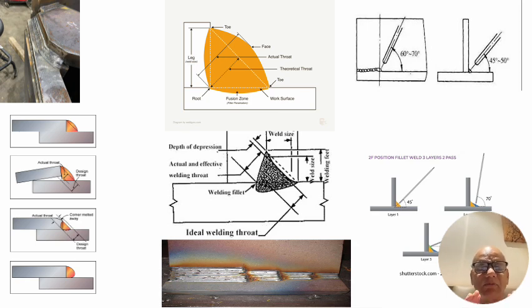So this is one difficulty we face, and as you see here, in different passes it has to be maintained. The fillet may not be achieved in one single run. There are a few methods, not very widely used, where in a single run we try to cover by little weaving, which I will show in the next slide, for nozzles.